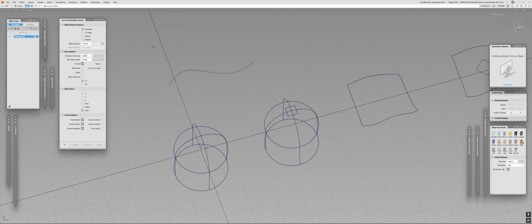Because of that, different systems use different tools to create thickness. Systems like SolidWorks, Fusion 360, and Rhino use tools like thicken or shell, while real A-class surfacing tools like Alias use offset commands. Offset commands in general exist in all the CAD systems, as well as vector and raster editors, so it is universal. And this universal tool, or better said its basic algorithm, is at the core of all thickening commands. So if you strip away all the bells and whistles, which are extremely useful, let's say from the shell command in Rhino, you will end up looking at basic offset functions at its core.